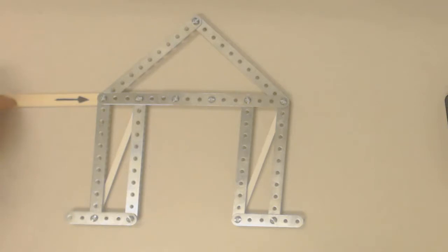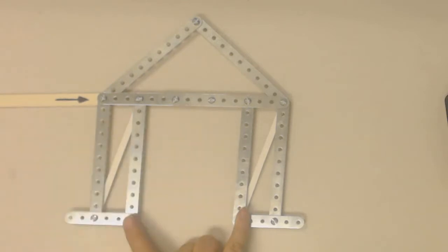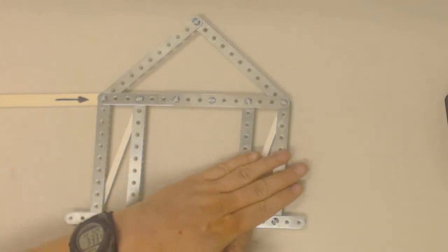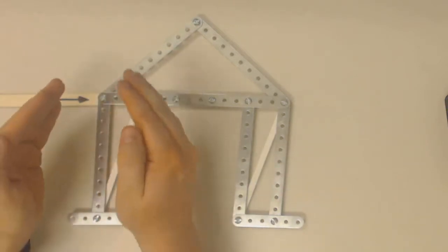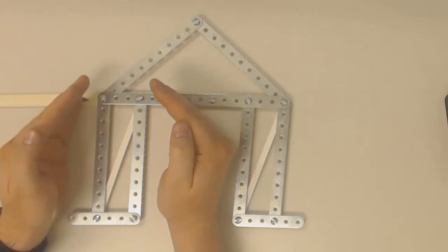Now the 20,000 pound load that's applied up here is assumed to be distributed evenly between these two shear walls. So if this is 20,000 pounds up here, then this shear wall is responsible for 10,000 pounds, and this shear wall is responsible for 10,000 pounds. So really all we have to do is analyze one of these with a 10,000 pound load at the top to see how the whole system responds.